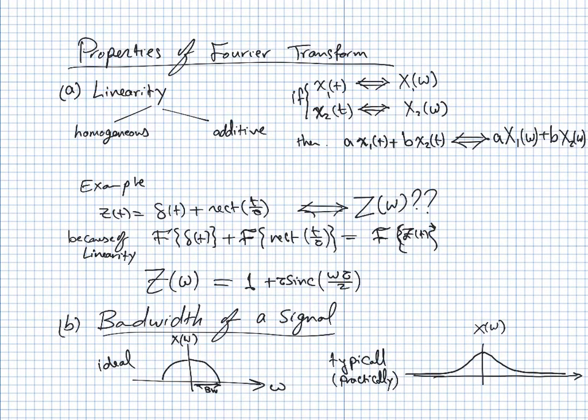There is the 3 dB bandwidth, which means that the value of the signal is reduced until it reaches half power, which means that the magnitude, don't forget that this X of omega is a magnitude, not a power, is reduced by 1 over root 2. So it's the magnitude multiplied by 1 over root 2, which is like 0.707. So basically you are looking for the point here where the value of this peak is equal to approximately 0.707 multiplied by the peak.